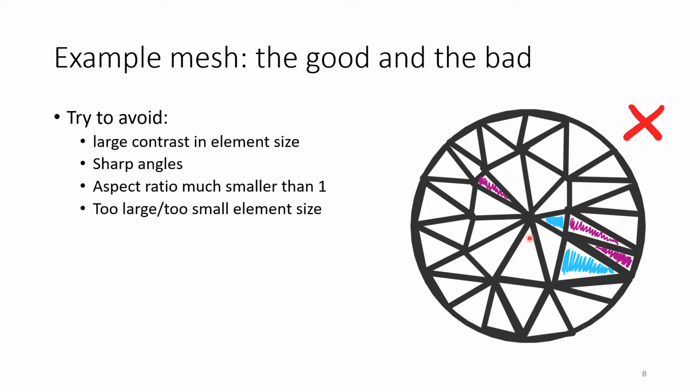And if you have a bad mesh, your solution might not converge, or other kinds of errors may occur. Your solution gets inaccurate, all depending on the spatial discretization. So having a good spatial discretization is an important starting point. You can do a lot of things wrong right from the beginning.